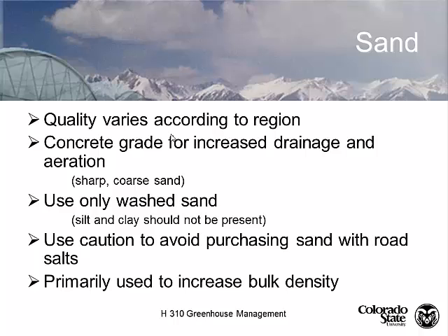You also want to make sure that you're not buying sand that's waste product from the Department of Transportation, because the sand that comes from the Department of Transportation is contaminated with road salt. So you want to stay away from that.